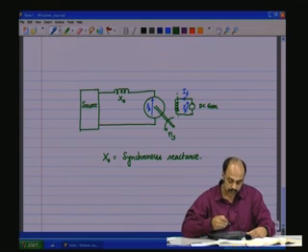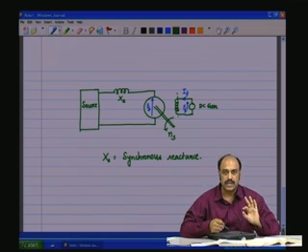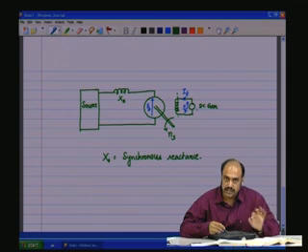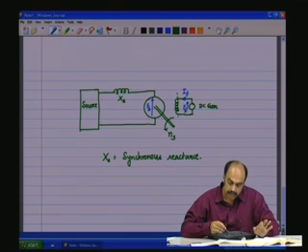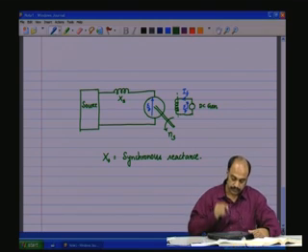So at this point, you note that the shaft is rotating at ns. ns is constant once fs is fixed, because p is fixed for the machine. So ns, the synchronous speed, is constant, which means the generator shaft is rotating at a constant speed, which means the induced EMF EF, the field EMF, is constant. Therefore, IF can be a constant value there.